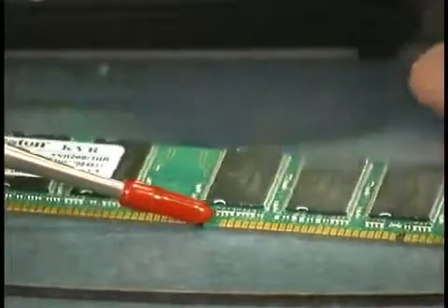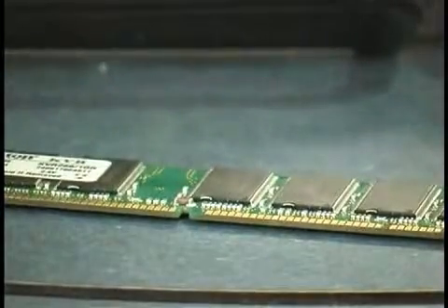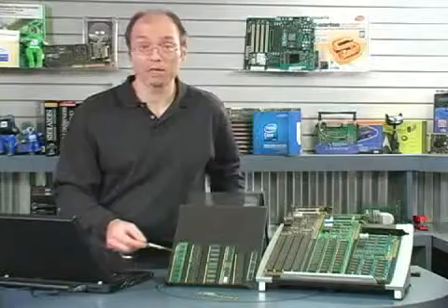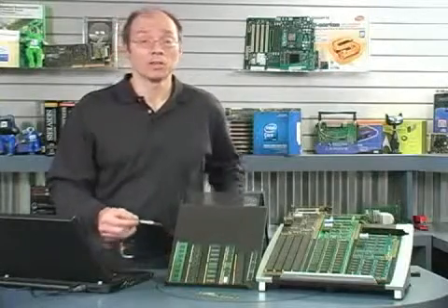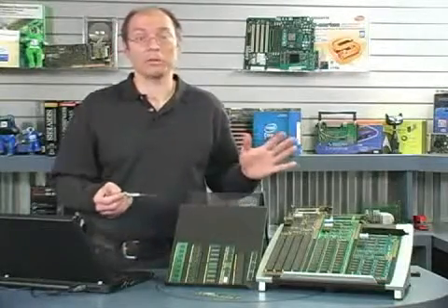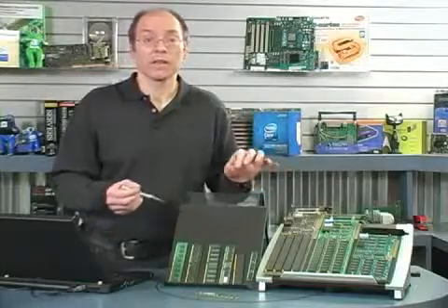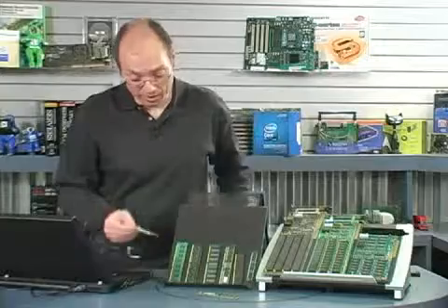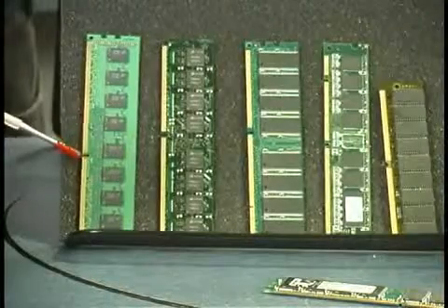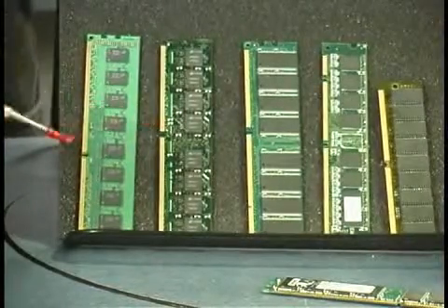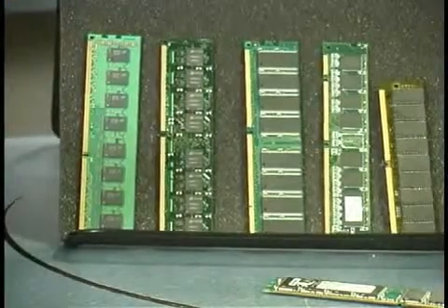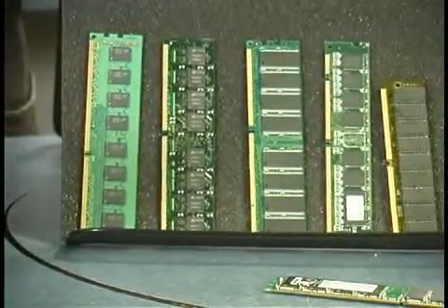Now, sometimes this can be confusing. For example, in the case of the DDR2 and the DDR3, they both have the same number of pins. They're both 240 pins, yet they're incompatible with each other. How do you make sure that the right memory goes into the right socket and in the right orientation? Well, if you notice, the notches on the DDR2 and the DDR3 are in different positions. So by altering the position of these notches, these keyways, they try to make sure that you can't plug it